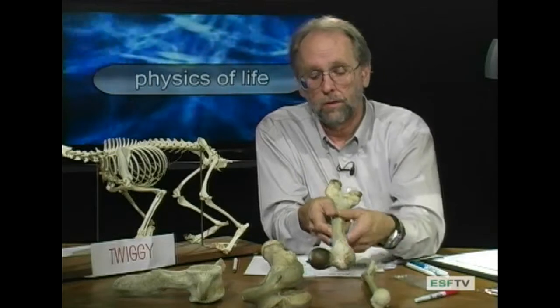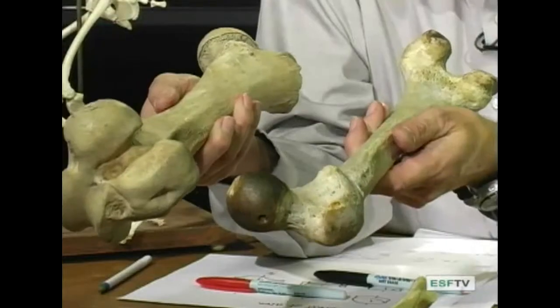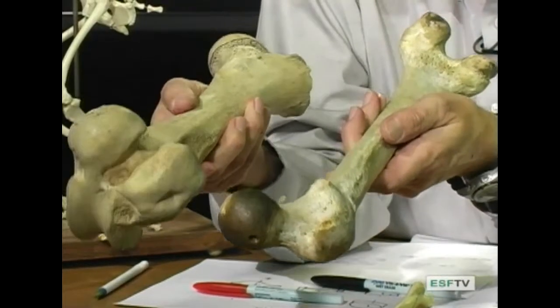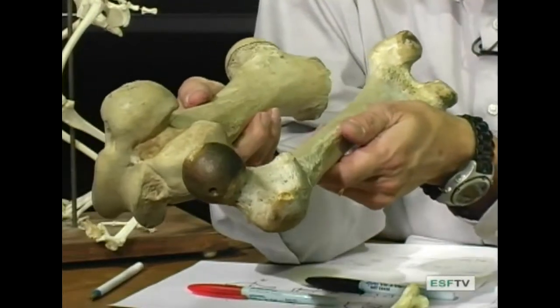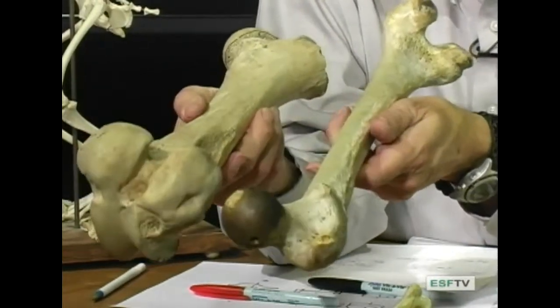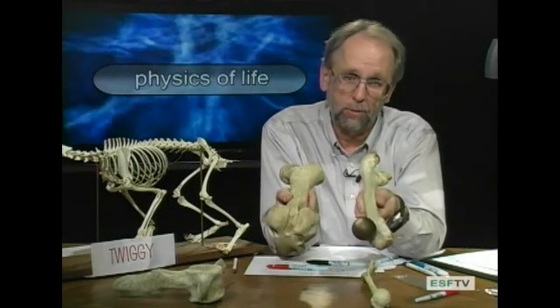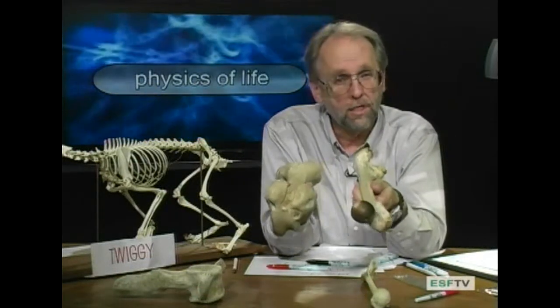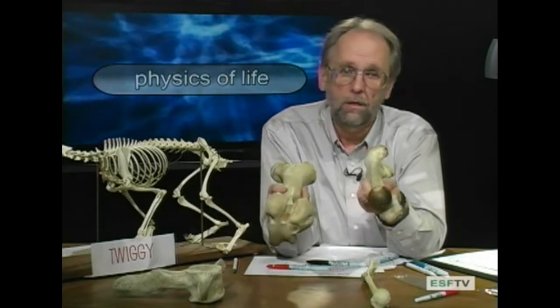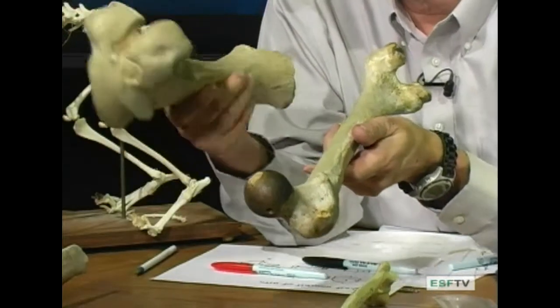And of course, we can compare these two bones here. This is a femur of a cow, and this is the femur of a human. Obviously, cows have to sustain much larger loads, and the lengths of these, this one is shorter, but not that much shorter, but the diameter is quite a bit different. Again, the second moment of area in the cow femur is going to be much greater than in the human femur. The same material characterizes both, but what's enabling this bone to hold up a cow and this bone to hold up a human being relates to the shape of the bone, namely the second moment of area of the cow femur versus the human femur.